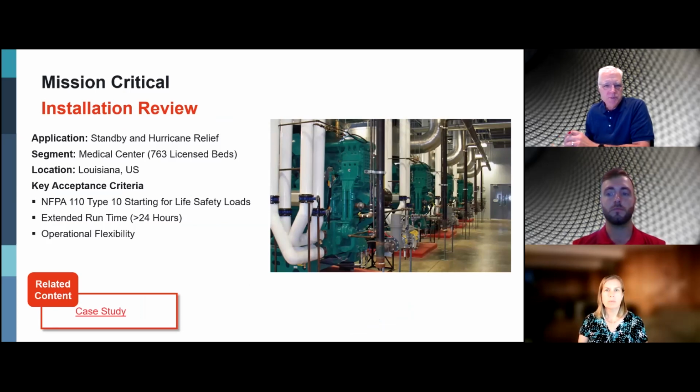Within the hospital, we have one 1750 kilowatt diesel application. We have 5 1750 kW lean burn natural gas units. We have some digital controls. We have paralleling switchgear, transfer switches. And the application is emergency standby along with supplemental power. And I'll explain what that means.